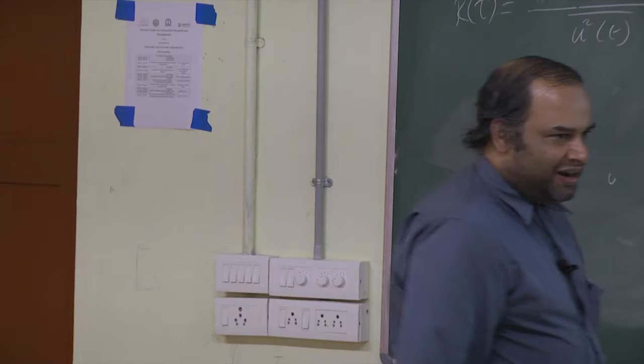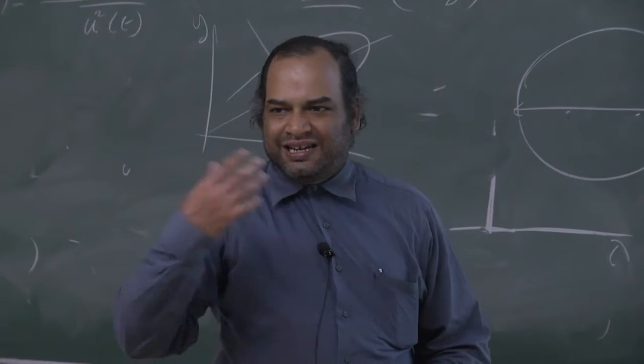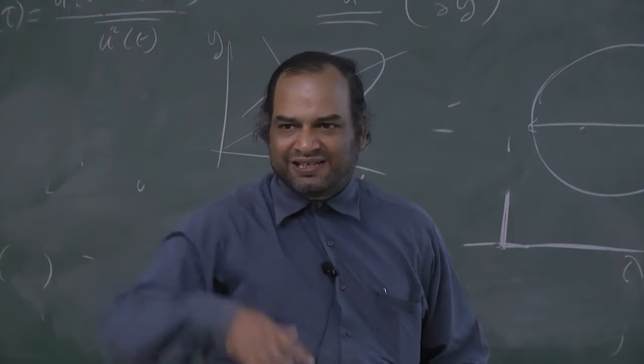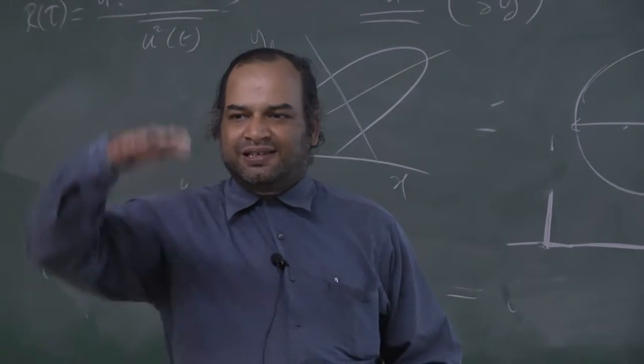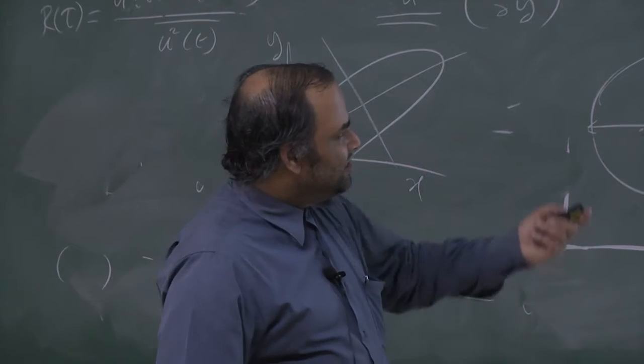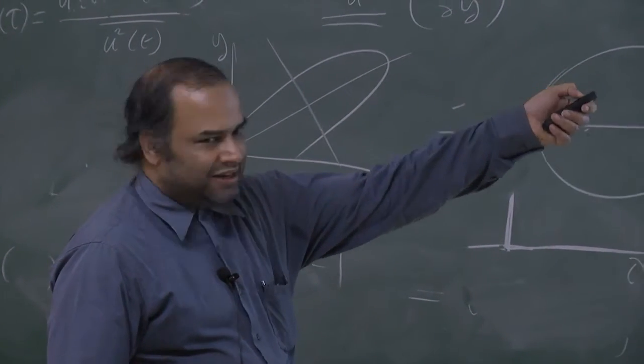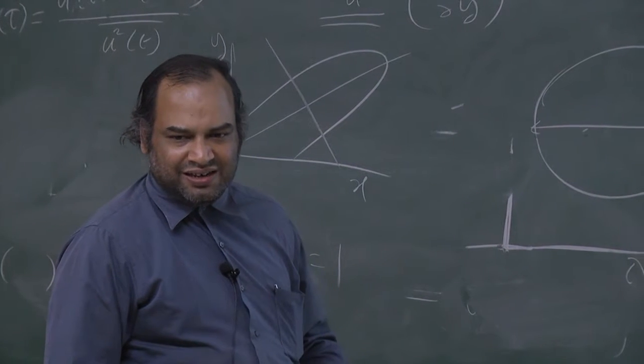So remember, I started by saying at the large eddy level, especially away from the wall, in the physical space, turbulence is almost inviscid in the outer portion. And that's clearly the case here also, where you see this part of the eddy, it's very inviscid.